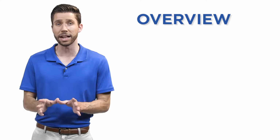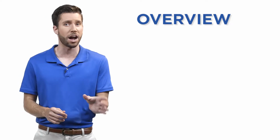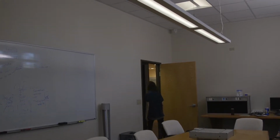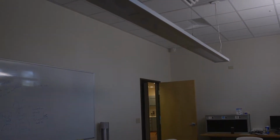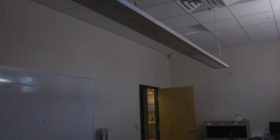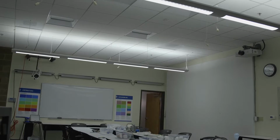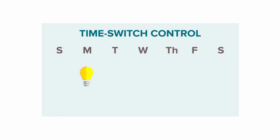Shutoff controls automatically shut off or reduce light output when a space is vacant or normally unoccupied. They're required for nearly all non-residential lighting systems in newly constructed buildings, additions, and alterations. Shutoff controls include time-based control and occupancy-based control. First, there are time switch lighting controls. Time switch controls allow for scheduling of lighting system operation based on occupant schedule, day of the week, and time.